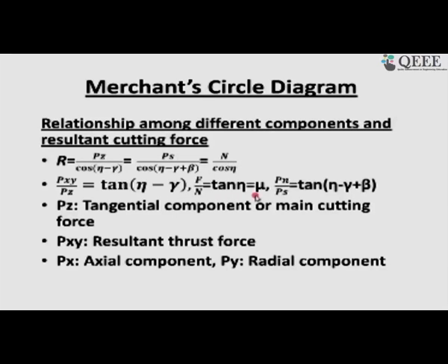friend, here we should be careful to make a statement. It is actually apparent coefficient of friction, because it is no more in the elastic range. This deformation takes place sliding in the plastic. So, it is our convention to call it apparent coefficient of friction or ratio of tangential force to the normal force.